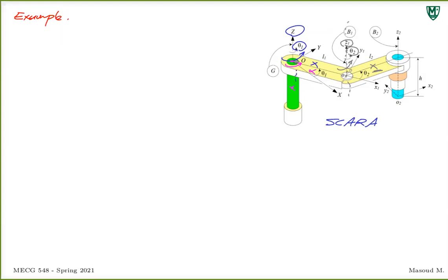The rotation occurs around it. You're talking about the revolute joint, right? If your thumb shows the axis of rotation, assuming that your four fingers represent the direction of the rotation, you usually go with the right-hand rule, so things are pretty established, and we can come up with uniform procedures.